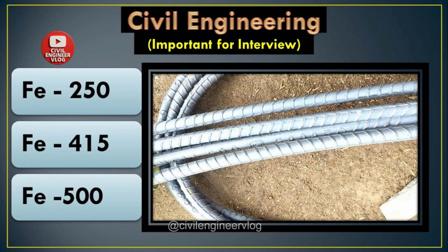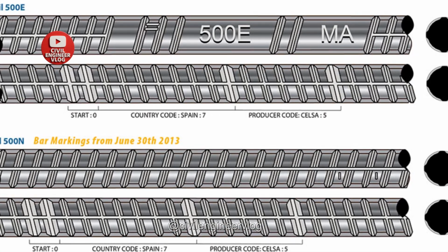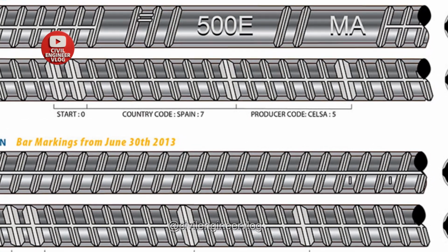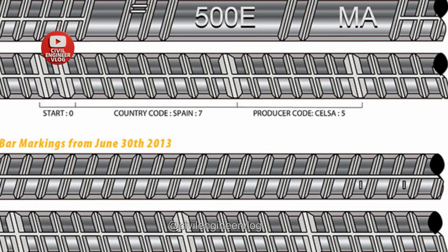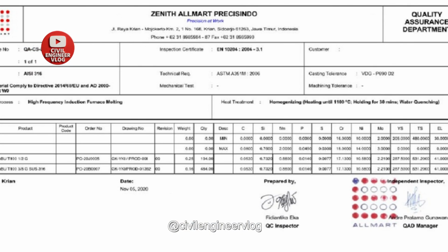Some local suppliers even sell fake branded rebars with forged ISI marks. Always buy branded TMT bars with a proper ISI mark. Ask the supplier for a lab test certificate. Do a basic tap test. A good bar gives a clear, ringing sound when lightly struck.